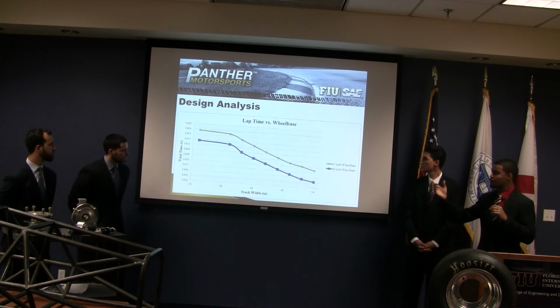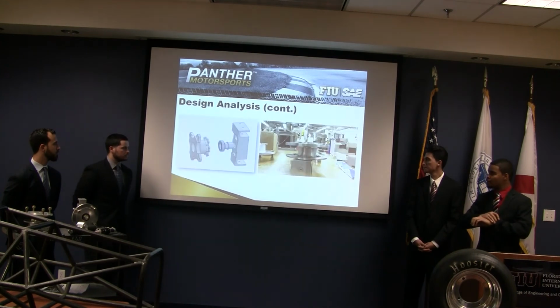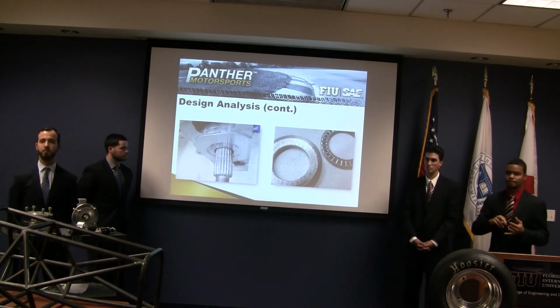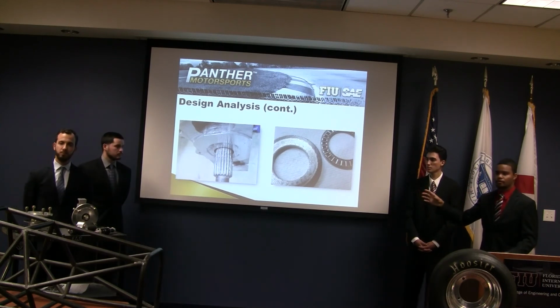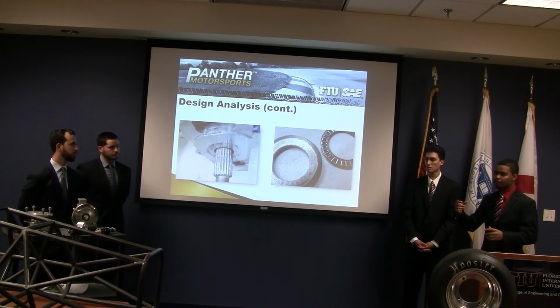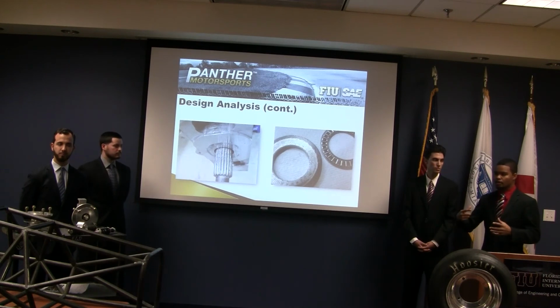And that's why we have the slide where we show you the thrust bearing and where it was going on. So then we did our research, we pulled up some Timken engineering manuals, and we looked into exactly which bearings are appropriate for the applications, and then we picked the bearing accordingly. And then afterwards, we made sure that the press fits, thanks to the help of Mrs. Acrylic, the fitment of the bearings pressing into the hubs and pressing into the shafts were good enough so that they would free spin without causing excessive binding or excessive stresses to the bearing. And that's how we modified from last year to this year.